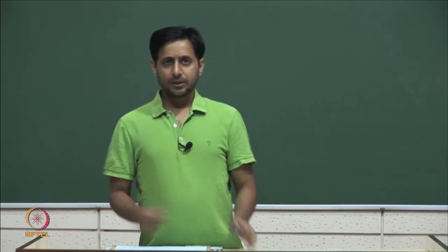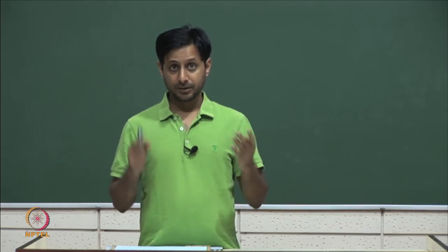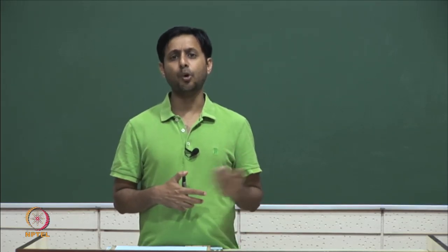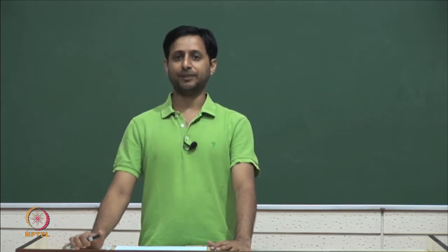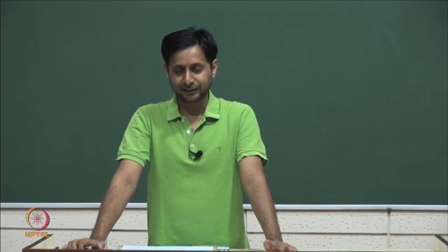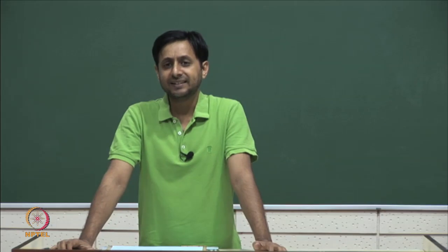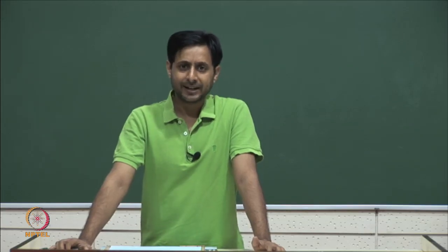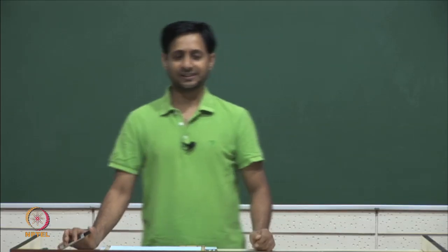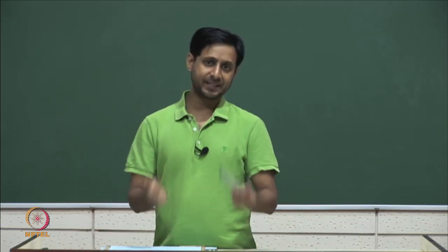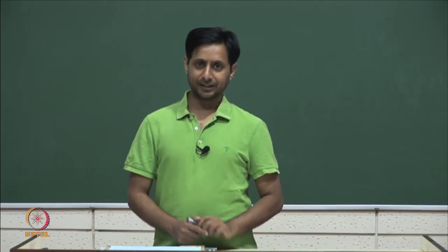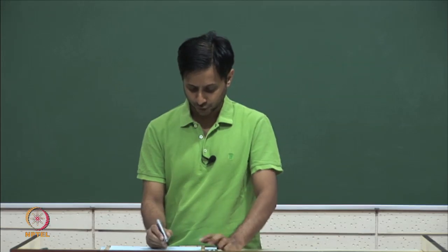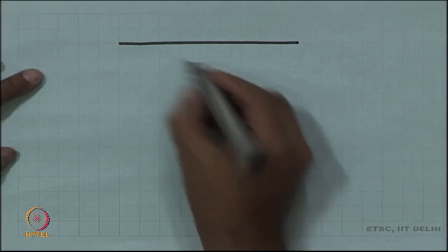Now, that is one thing that we did in the last class. The other thing that we did was we replaced the load, that is the resistor on top of the differential amplifier, with a PMOS device, and that is called an active load. The PMOS device is very nice because it behaves like a current source. So, at DC it provides just the right amount of current, whereas for the signal it provides a large resistance, which is exactly what you wanted, and that basically takes over the role of the resistor, and therefore, it allows for better swing hopefully. So, let us take a relook at that structure, and let us try to understand the performance limitations.